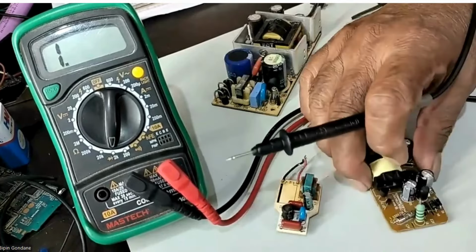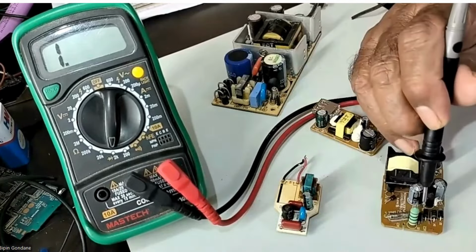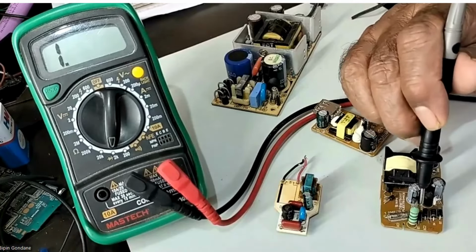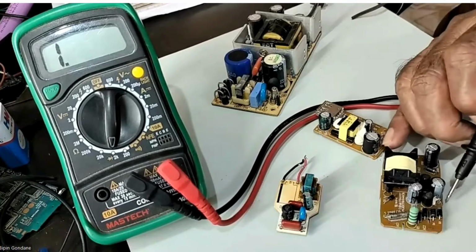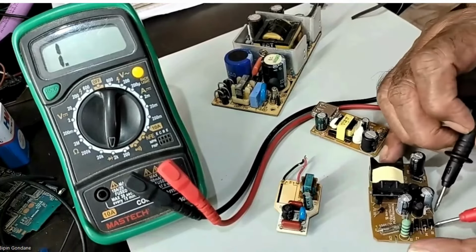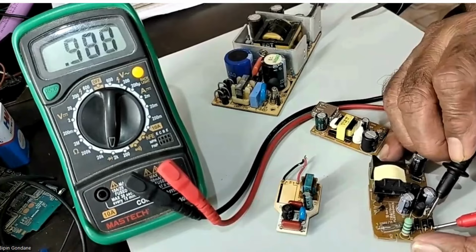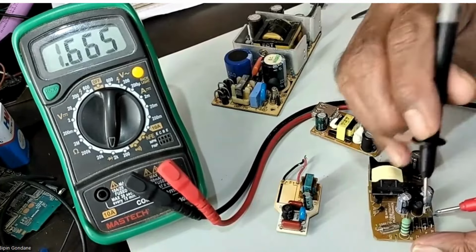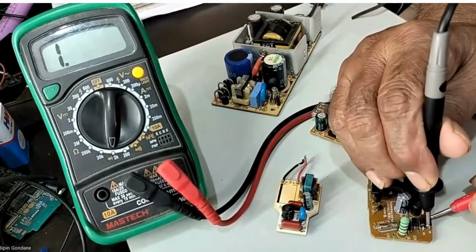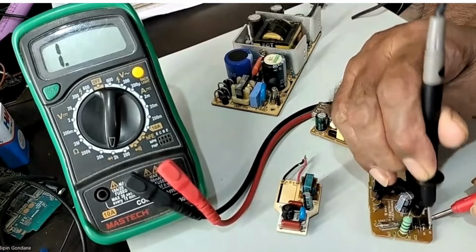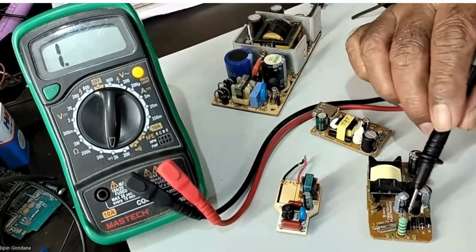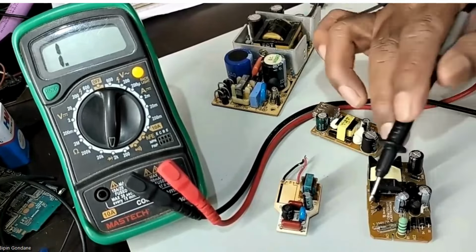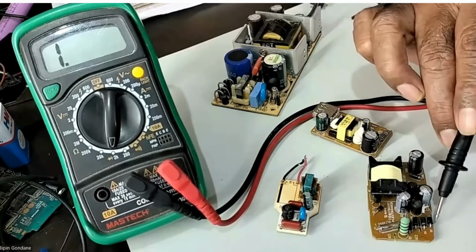Now the second part: immediately after that you have to check the rectifier circuit, that is this bridge rectifier. Mostly the bridge rectifier is given with four diodes, and you have to check all four diodes. Likewise, I am just checking. It is showing one resistance. Reverse it. No resistance, so this diode is okay. Likewise, you have to check all four diodes. So the second part we have checked: after the fuse or fusible resistor, we have checked the diodes.